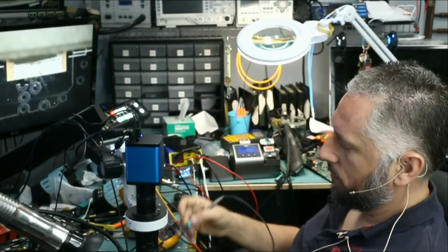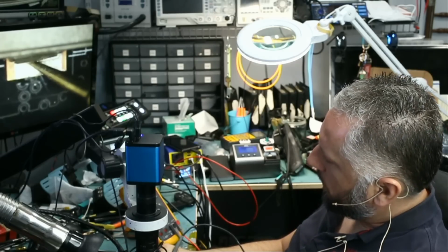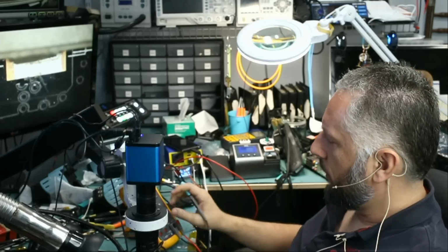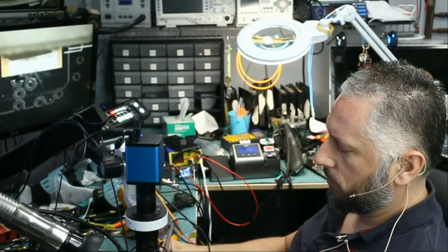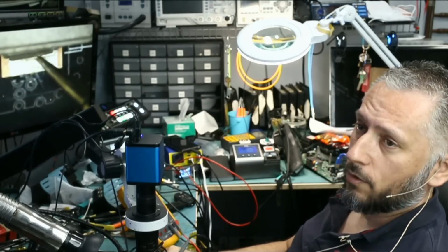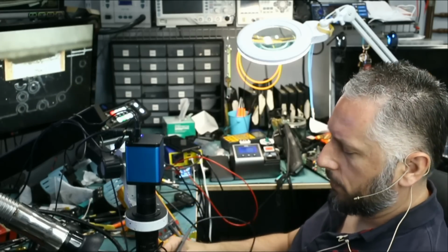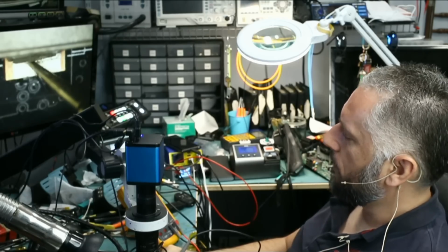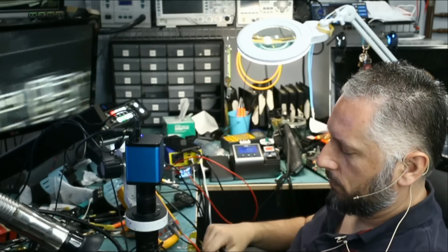If we measure in ohms mode, what readings are we getting? Right now it's 78K. The board is still hot, so the reading may not be accurate, but it's not in the ohms anymore. It's in the kilo ohms. Diode mode, one more time. 0.3 voltage drop. It's gonna probably rise up to 0.4 after the board cools down a bit. 0.314, 316, 317. It's gonna go up to about 0.4, 0.47.